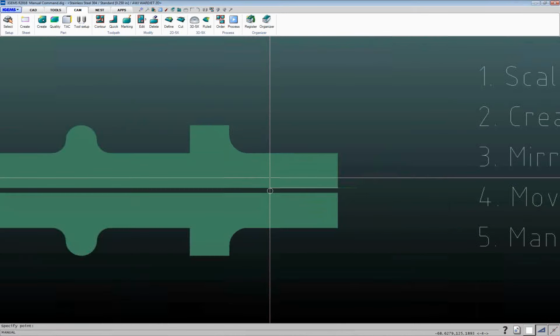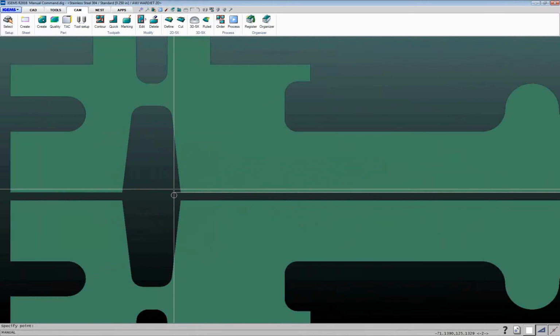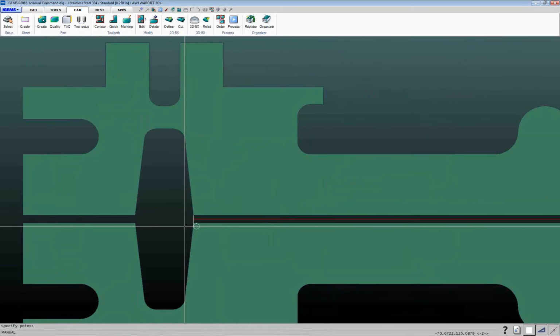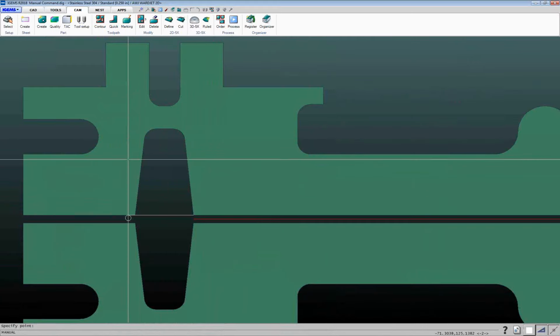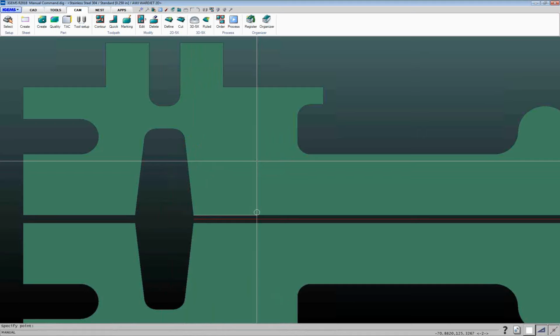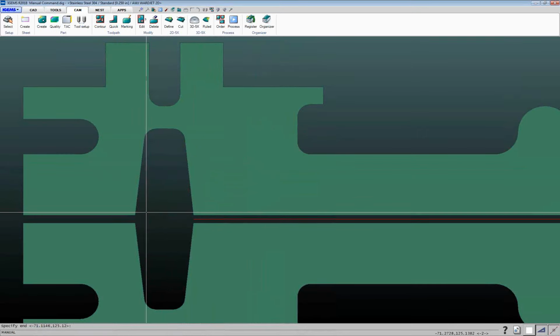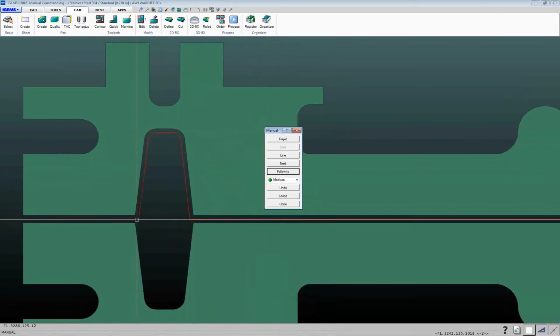And then I can get into my actual cutting. So I can use the line command, and I've got a couple ways of doing this. What we can do in this case here, I'm going to come down to this point here, and once I click on that point, it adds that red line there for my tool path. And now I want to go around this area in here, which isn't a line. So if I hit enter, I can use this follow to option and say, all right, follow that contour over to this point here, puts my tool path in there.